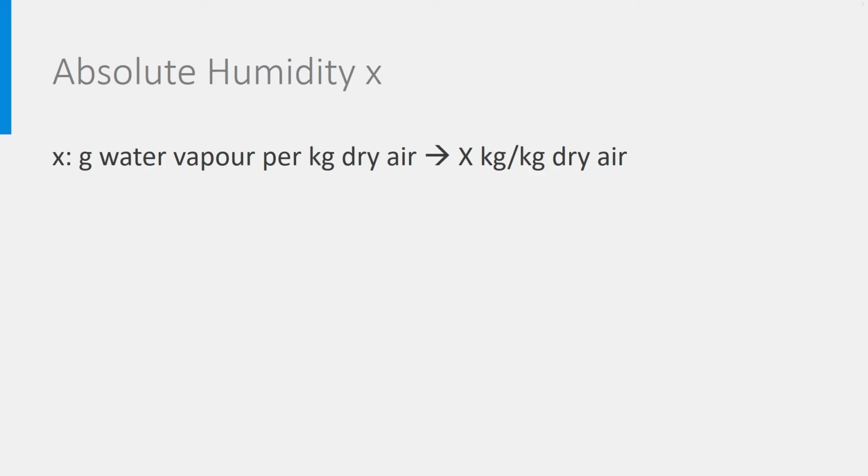In this lecture, we will focus again on the absolute and relative humidity and the water vapor pressure and derive the equations the Mollier diagram and psychrometric charts are based on. First, some considerations about the absolute humidity X. In the diagrams, it is given in gram per kilogram, but in all equations it must be converted to kilogram per kilogram, which I am indicating with a capital X.